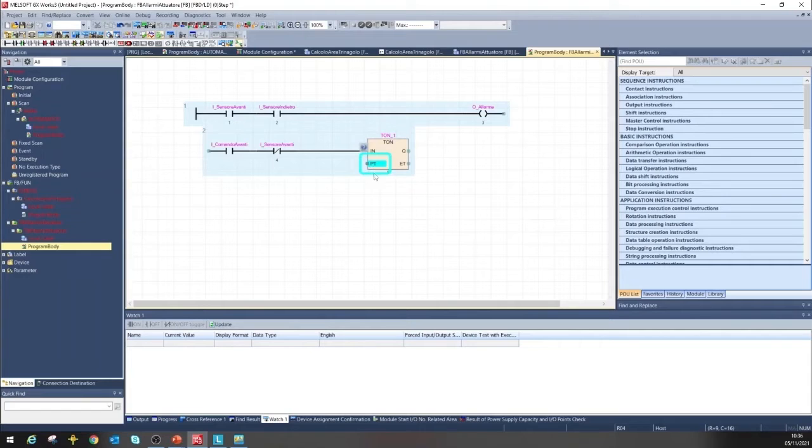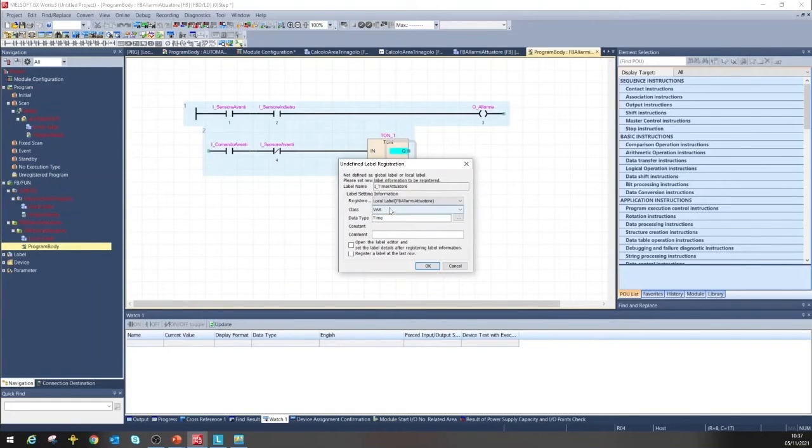However, at the input, it will want a timer. So if we place our cursor near the entries to PT, it tells us that it wants an object of type time. For us, it will be an input, because someone from outside who will use the FB will define the maximum time for the detection of this alarm on this particular condition. So we call it timer.